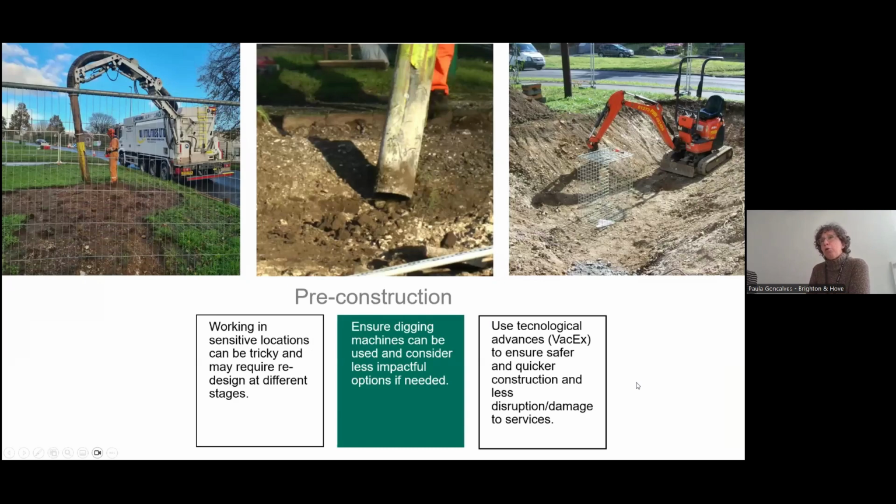If you do have to do inspections where you have services, there is this machine that we only learned about halfway through. If we had known this, we would have done our inspection holes using this machine, which is a big vacuum cleaner. And it's amazing how it sucks up everything, topsoil, clay, everything. It goes into the truck and they move it. You have to stop traffic and all sorts of stuff, but this is highway management.